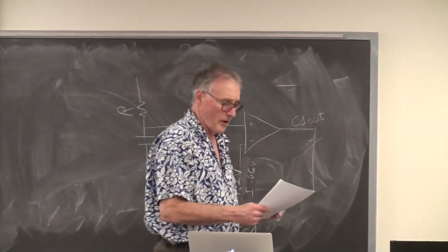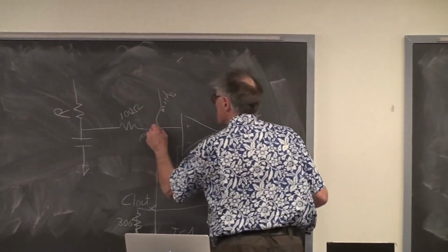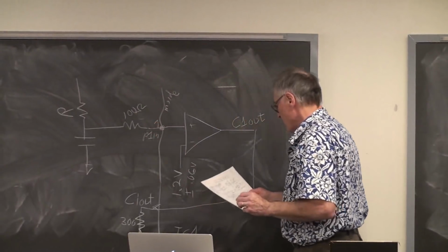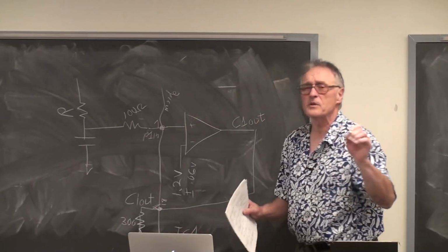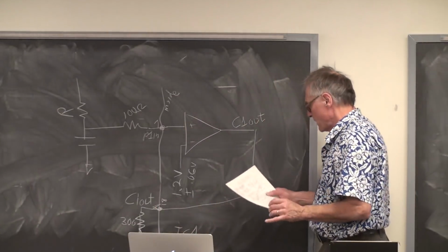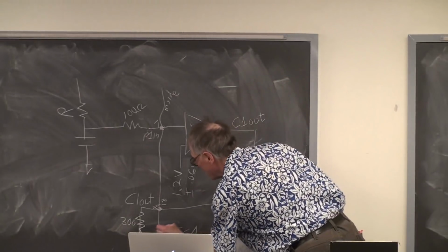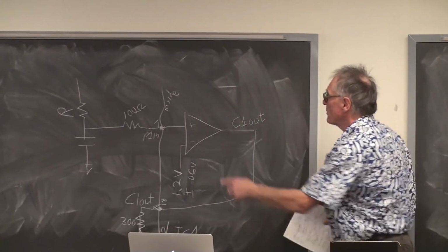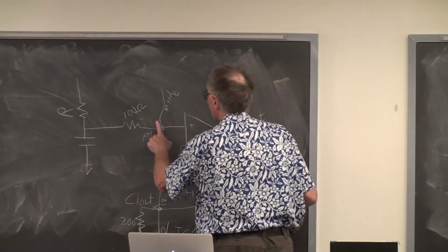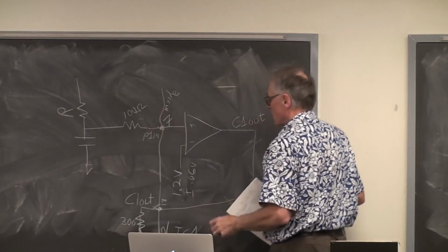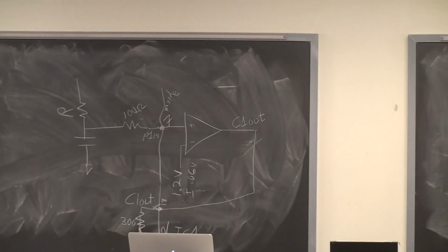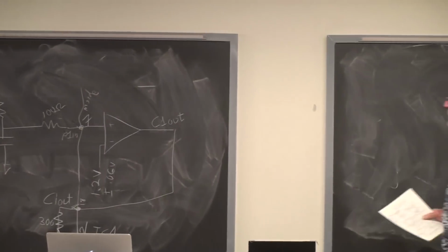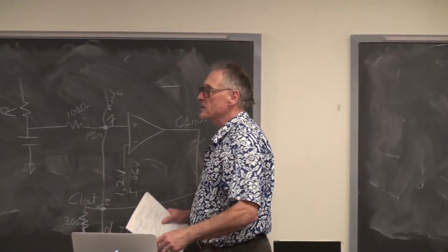So what we're going to do, though, by the way, on the package this is pin 7. We're going to map this to pin 18. There's a step using the peripheral pin select I haven't talked about yet. And we're going to map this to pin 2. So pin 7, pin 18, pin 2. Pin 7 also happens to be known, oh, this gets so messy.